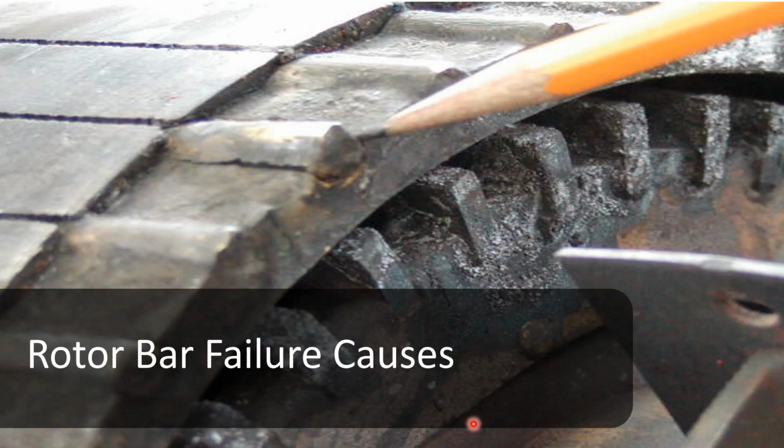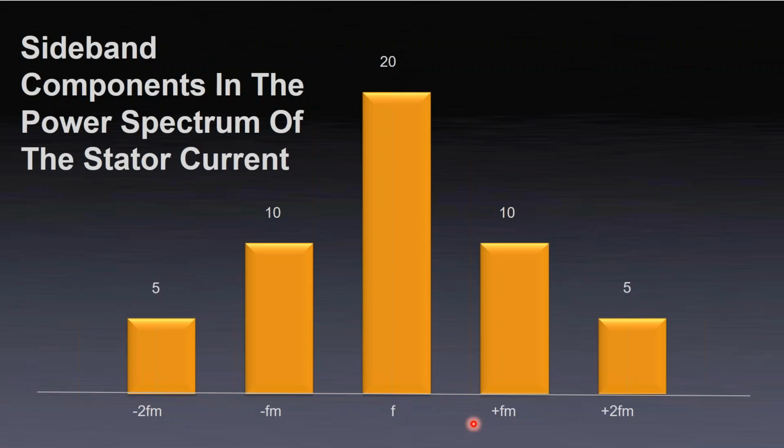So as we can see here, a rotor bar can be completely or partially cracked. And these can be due to things like manufacturing defects, of course, frequent starts at the rated voltage, thermal stresses, and of course, vibration. What we're looking at here is sidebands or interharmonics. So there are fundamental frequencies here in the middle.